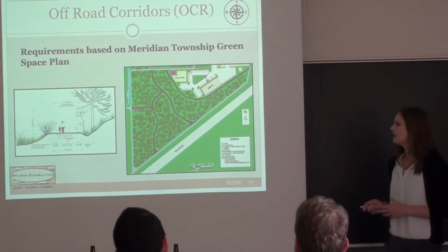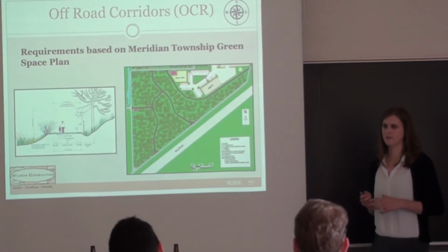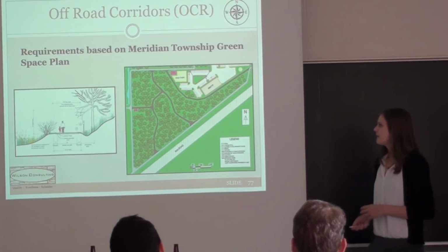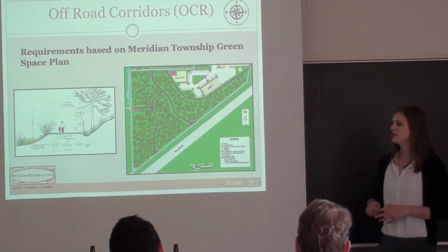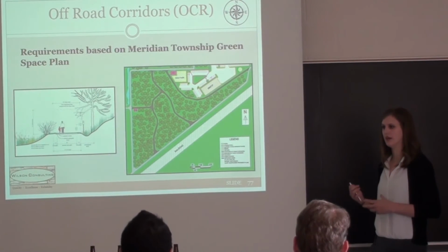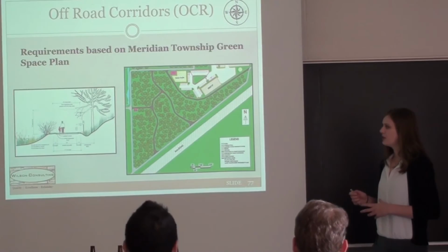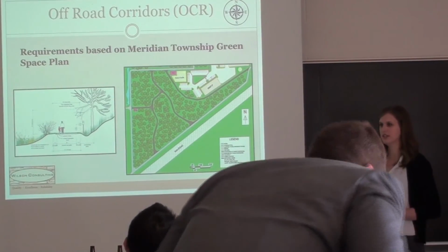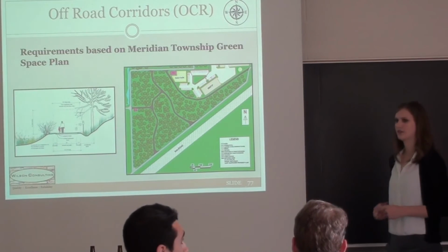So based on this, they wanted to have a 3-inch asphalt layer with a 5-inch crushed aggregate base. And for this aggregate base, we want to use the HMA layer that we're ripping up in the parking lot and also on Marsh Road and use it as the 5-inch crushed aggregate base just to recycle and to not have to increase costs for new material.